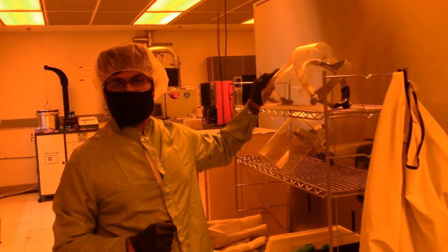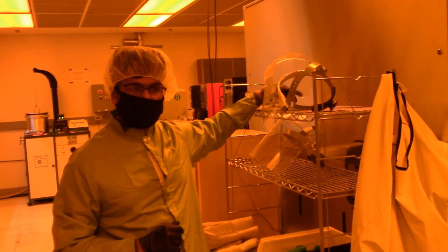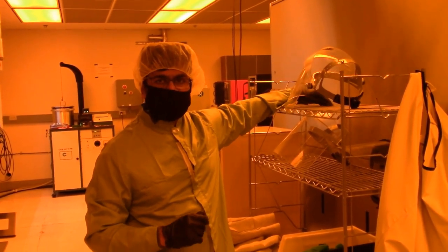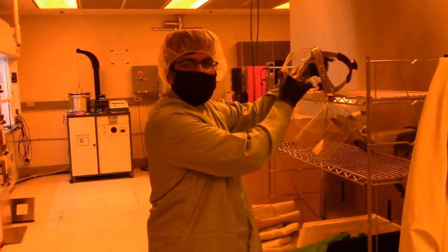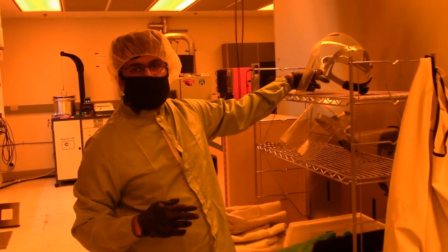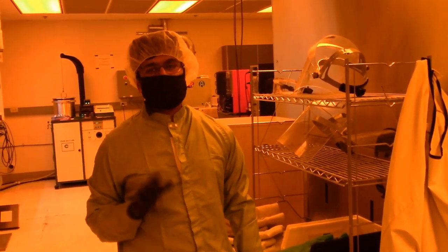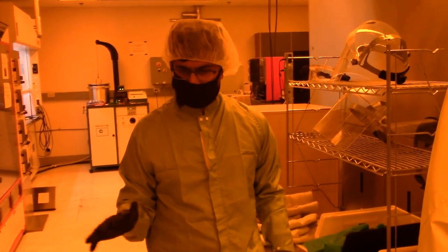Acid etches are usually done using a buddy system where another person, for example, Shirso, who's shooting with me, is going to accompany me while I'm doing this etch. You should make sure that you never do acid etches alone.